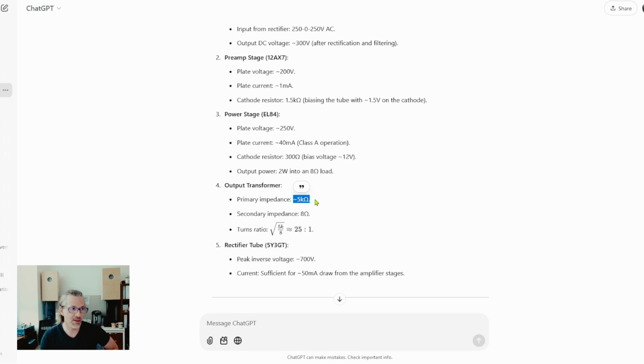And it's not just this, but in real life, this is your method that you can match a loudspeaker to an amplifier by trying out different primary impedances and see which synergizes the best with the loudspeaker. And that's why when you have a specific tube amplifier with a specific output transformer, it will synergize really well with certain loudspeakers and won't synergize at all with others, because the distortion spectrum and the power delivery spectrum will match certain speakers better and will not match other speakers that well.